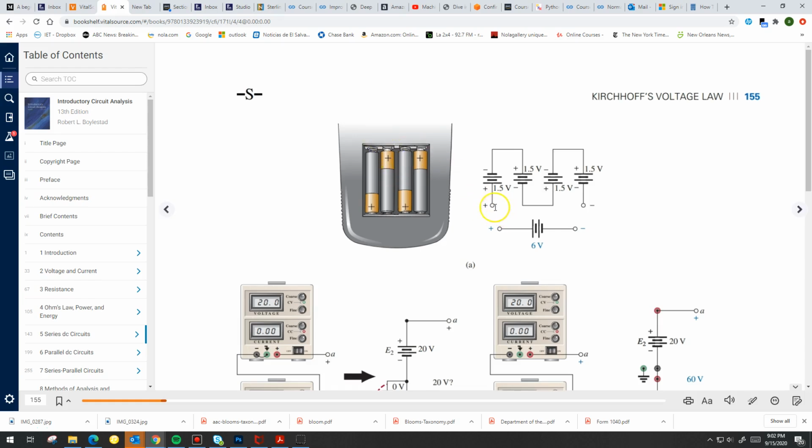So doing that allows you to go, and again, look at this connection, right? It's also a series connection, okay? And you can tell that by following the path. It's a single path, a single string, and you have two of the batteries connecting to a single point. These two are connected at a single point. These two are connected at a single point. They're in series, right?